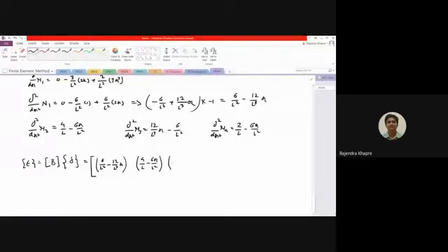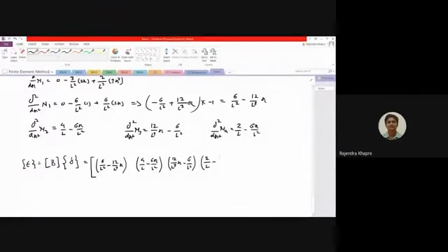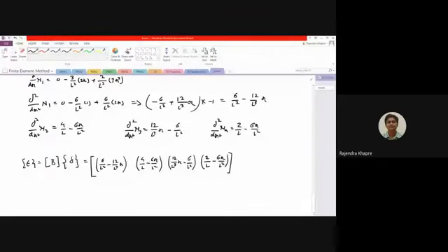And the third term will be something like 12 upon L to the power 3 into x minus 6 upon L square. And the fourth term, which we have just calculated, is 2 upon L minus 6 upon L square. This will of course be multiplied with W1, theta 1, W2 and theta 2. So this entire matrix is nothing but your B matrix, that is the strain displacement matrix.